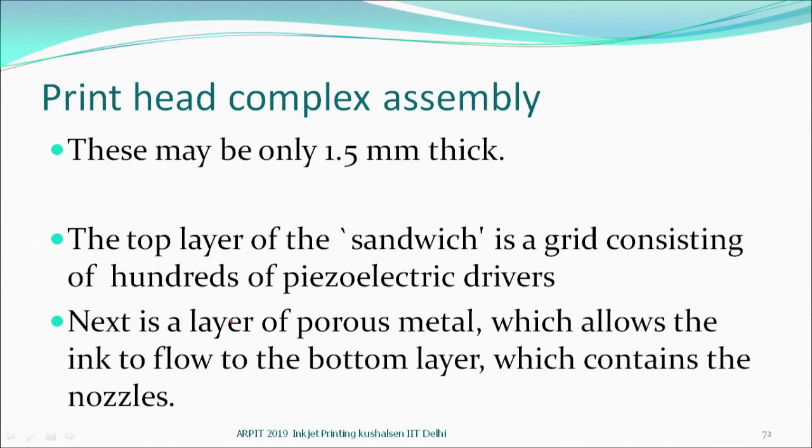So, you have a sandwich grid which contains drivers, and you have a layer of porous material which allows the ink to flow to the bottom layer which contains nozzles. All that could be very thin, because so many of them have to be put in the assembly. And therefore, this print head is not only just the heart, but is one of the very costly elements of a printing machine.